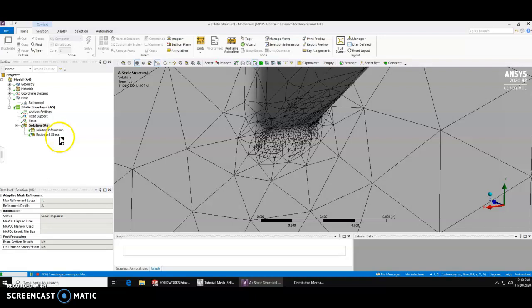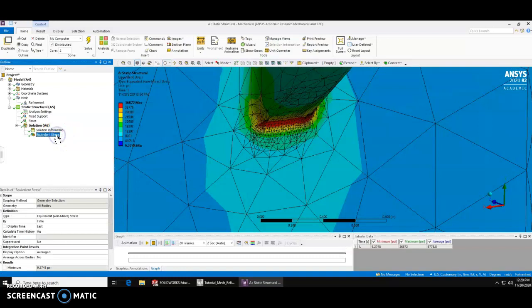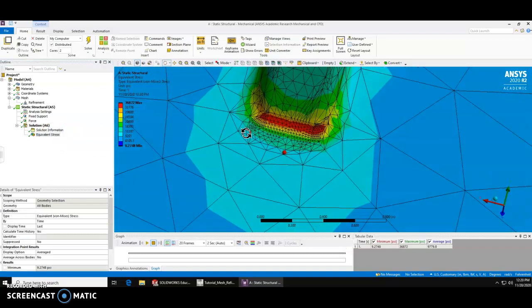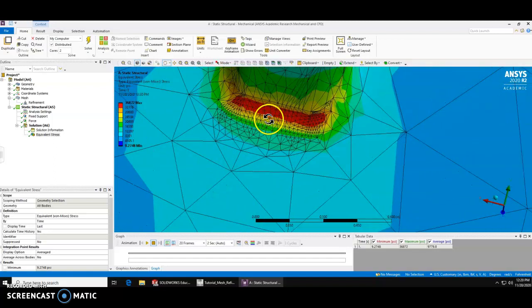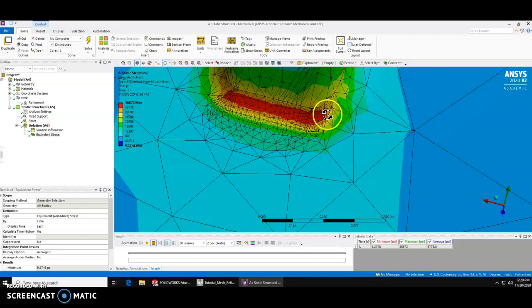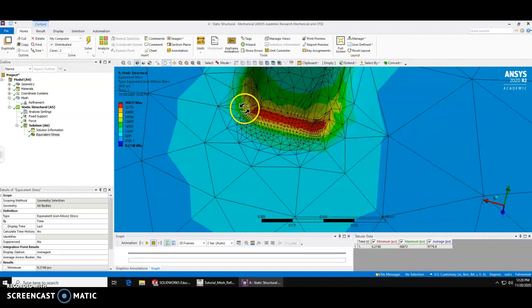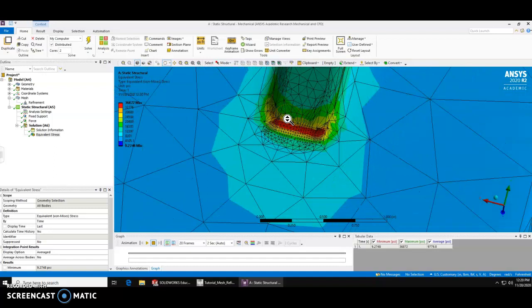We've just got this set up to do a von Mises stress. Take a second here for it to run that. Okay, so it's completed, and now you can see we're getting that stress area. So you see the change in color is happening pretty quickly, a pretty steep gradient around here. And we have a little bit of an irregular shape. It's not too bad in this case, but I guess in certain situations, if you have a bigger moment arm over which your force is acting, this might be more extreme, or maybe if the support is smaller.